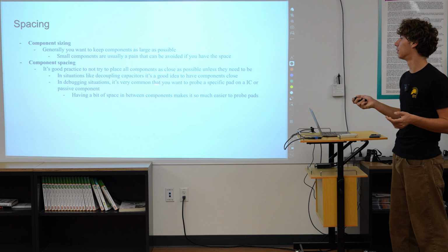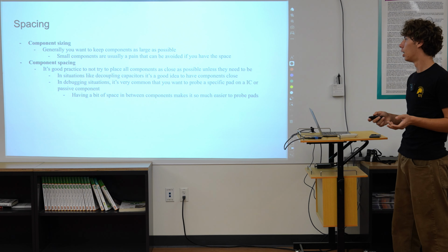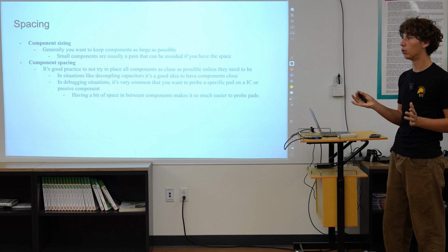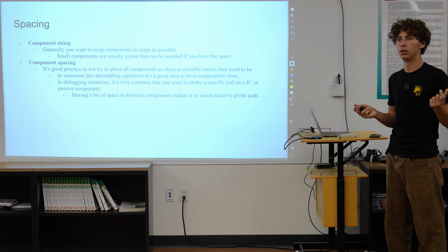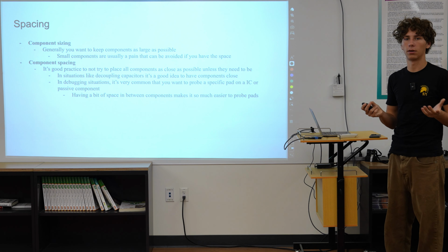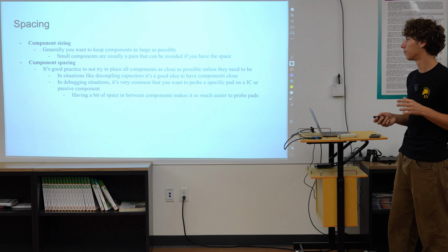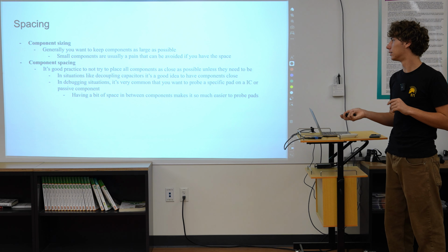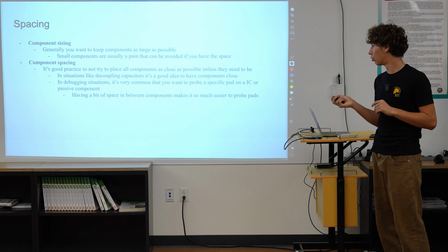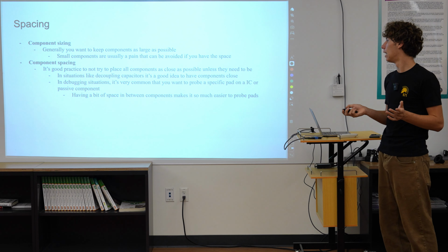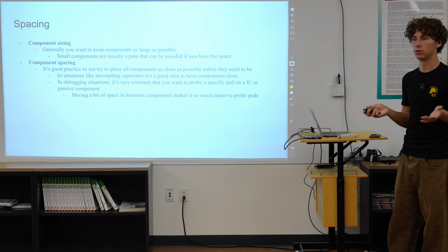Like situations like decoupling capacitors, you have to have them close. But in other scenarios, you can have them decently far away, to the point where if you end up having to repair the board and swap out a component, you can do that with a soldering iron and not just have to throw the board. In debugging situations, it's very common that you want to probe a specific pin on an IC that might not have been pinned out to a test point, and having a bit of space in between components just makes it so much easier when doing that.